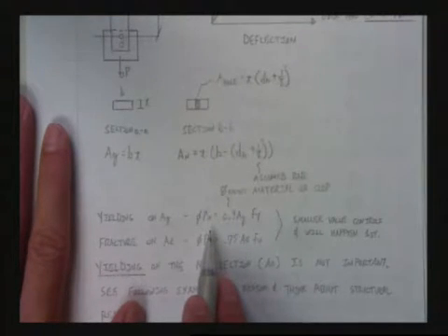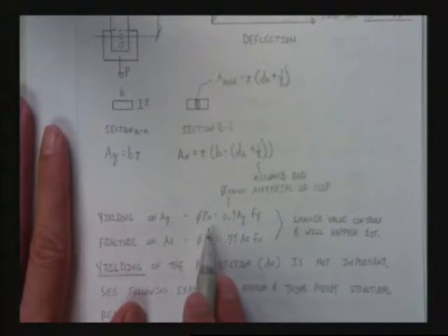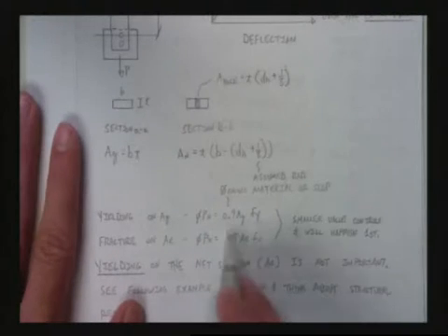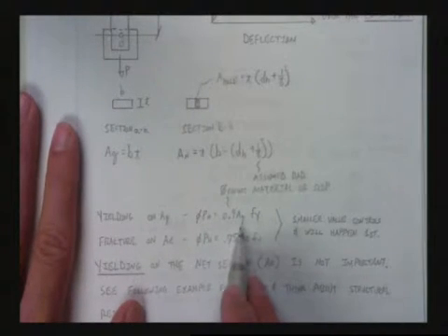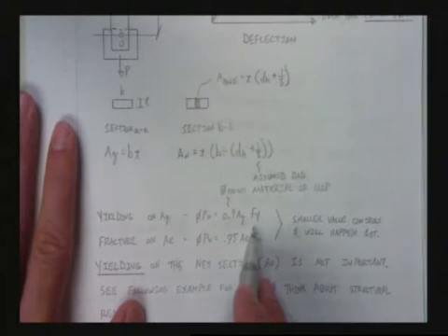The factored capacity, the nominal capacity. It doesn't mean when it's going to break. That means when it's going to break with a phi factor placed on it. Yes? Great. We use phi, 0.9, times AgFy. What's Ag mean? Know your gross. Area gross, that's right. And what's Fy mean?